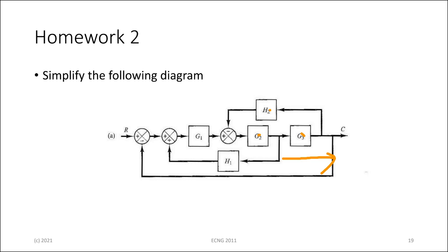Can I do this? G2 by G3. G2, G3, after moving the line. Yeah. Right, you have to move the line first, and then you have G2, G3 over 1 plus, negative feedback here, 1 plus H2, G2, G3. Yeah, exactly. So you shift that, and then you simplify it, and then you'll get a block within a block to simplify again, it seems. Yeah? All right, so